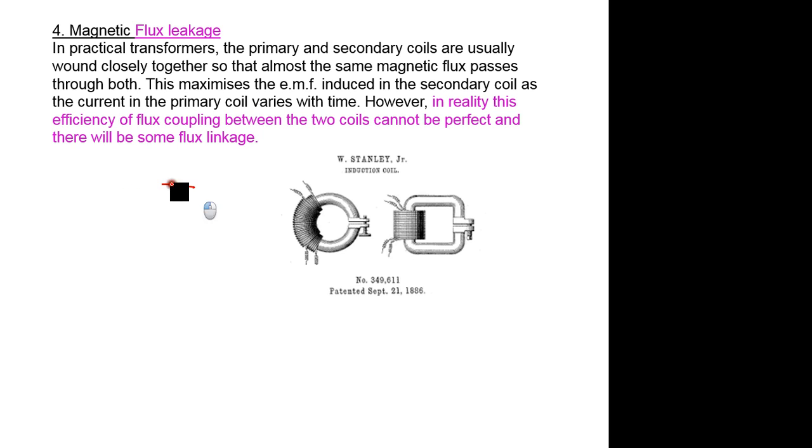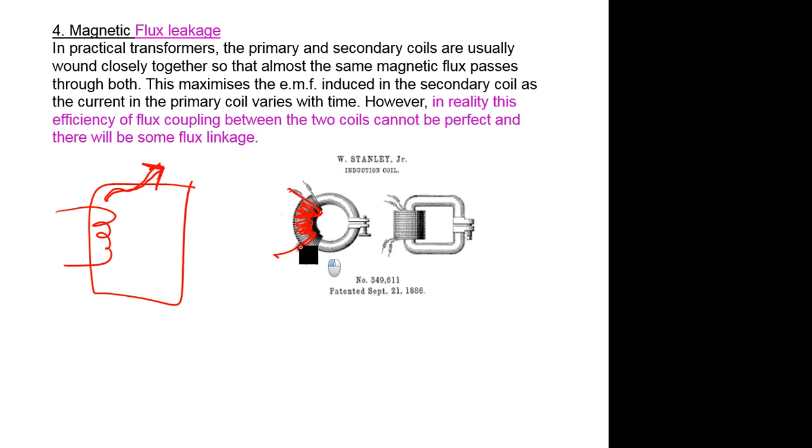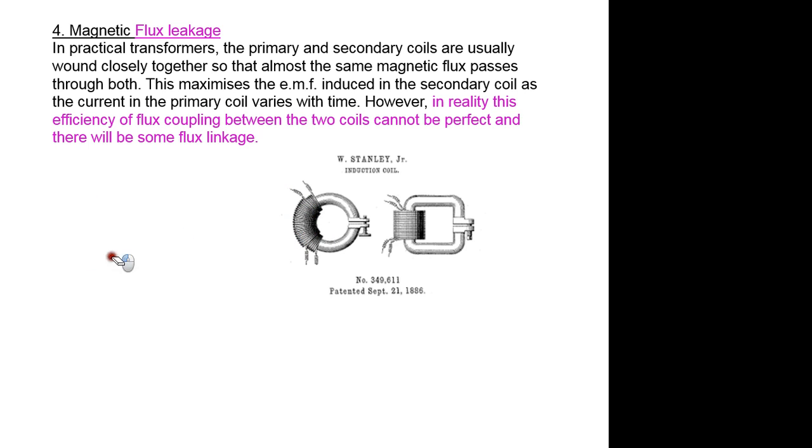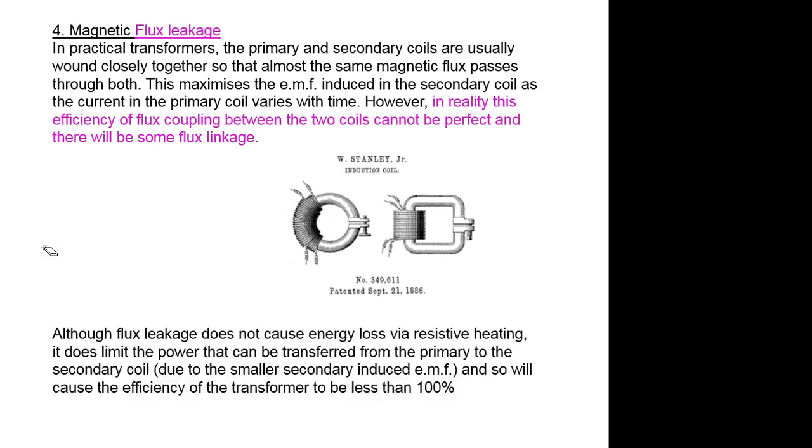It's because if you connect on opposite ends, there's a chance for the flux to escape. The flux that you generate can escape. But if you put it like that, you will capture as much of the flux. The red one will capture as much of the flux as generated by the coil on the inside. You overlap the coils completely, you will capture most of the flux. This is a very smart concept. So here they also show you that what you see in the circuit diagram is not the same as what is in reality. Right. That's that.